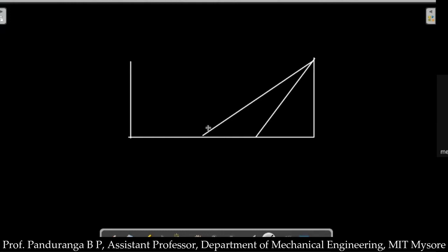If it is a reaction turbine, or if it is a radial flow turbine, we cannot use common base because the base values will be different. Here in this case, the base is the tangential speed of the blade, that is u. So here I have drawn a velocity triangle. Now I will name the parts.